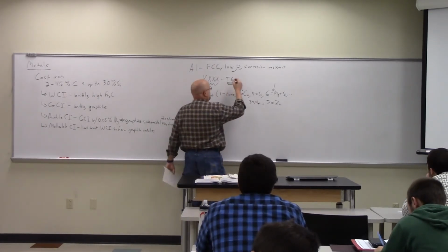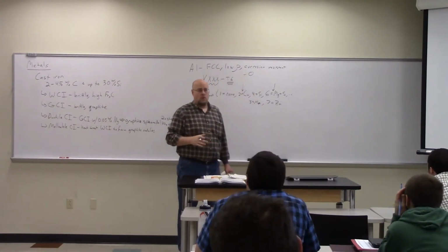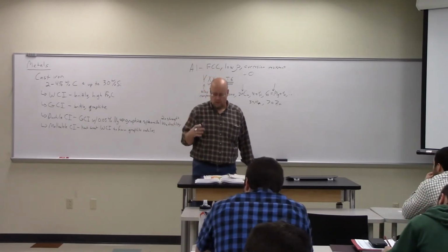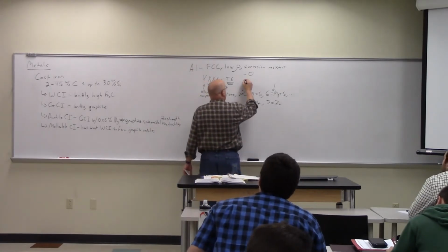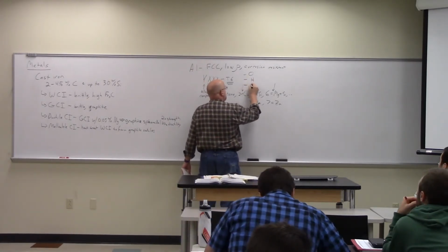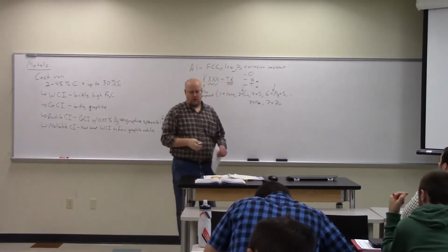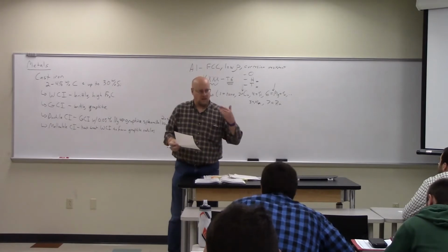the designations that you're going to be most interested in are O, which is fully annealed, so there basically is no heat treatment. And then recognizing that H and T, with some number after them, are the two broad categories. H is hardened, and T is tempered.